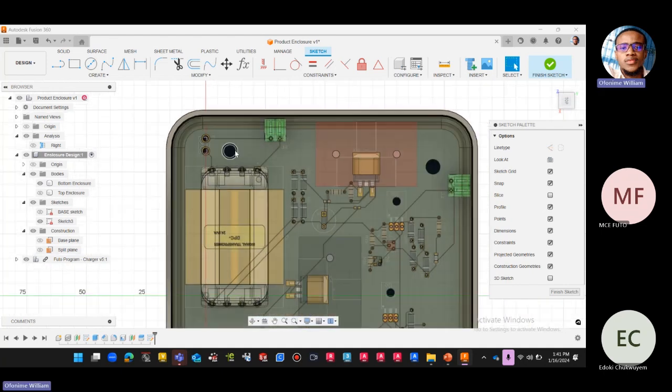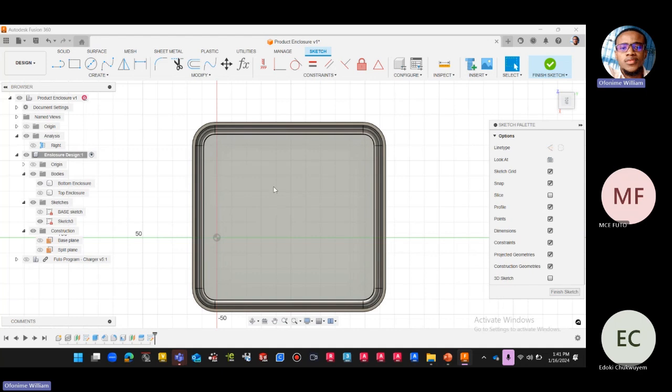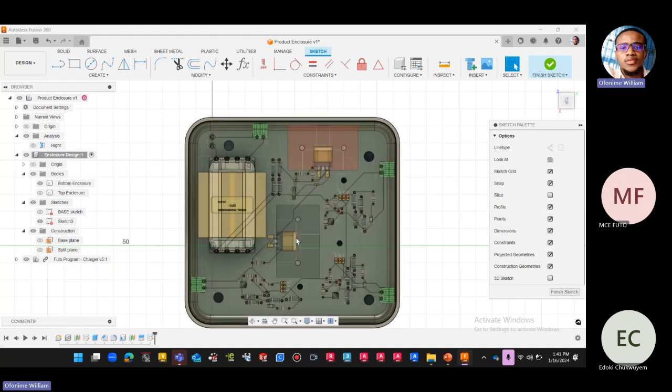My ask, why projecting? I need to know where the circles are, but not on the PCB. I need to know them on this current sketch. Can you see now there's nothing on this sketch? That's where we are currently drawing, but it's there on the PCB. So what I'm doing by projecting is more like a projector that you use. You're taking that geometry from somewhere, maybe that's existing on probably another product or whatever it is, and you're replicating that exact signature now on the current space.